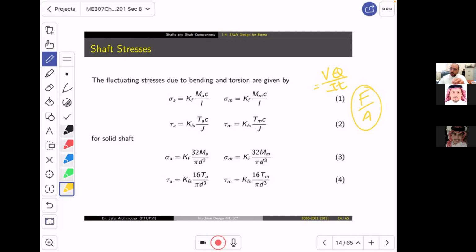But just like in your turbine shaft, if you apply a torque like the one in the problem for the project, 395,000 Newton meter of torque, if you go and calculate the shear stress tau equals TR over J, you will get a high value. Remember, ya shabab, if we use low carbon steel alloys with a yield strength of maybe 400 megapascal, what did we tell you about the yield in shear?